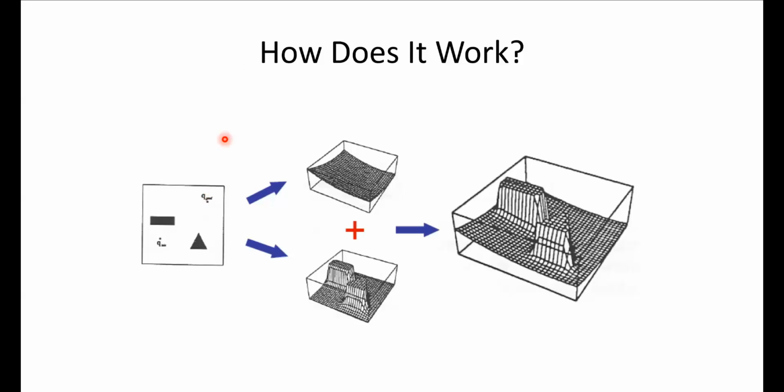Then I can come up with two different components to my potential field. So I can create this surface that just gently rolls me from wherever I'm at towards my goal, right? So I don't really care where my starting position is. It doesn't affect this choice. All that affects this choice is where my goal is. I want to make sure that that's a global minima.